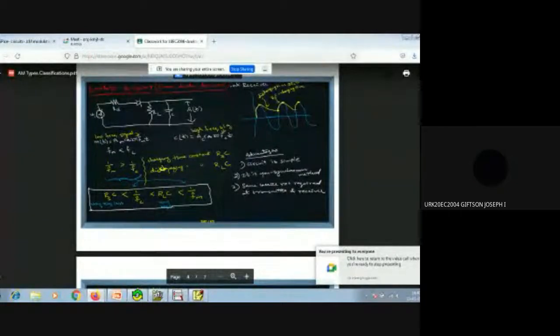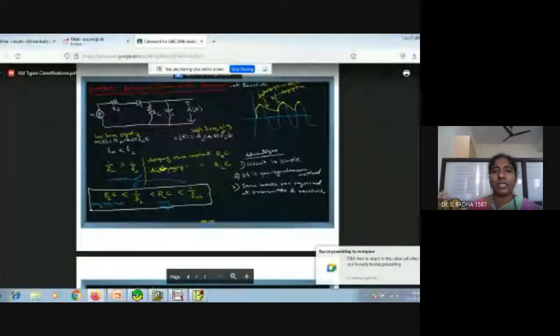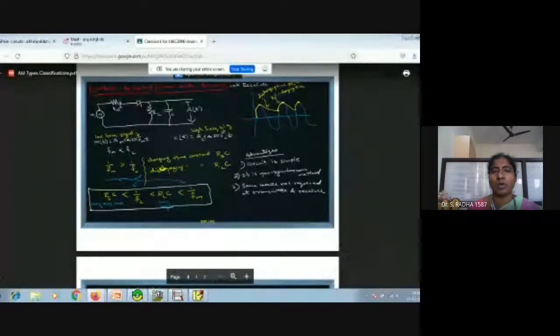So we have to give the modulated waveform. For the envelope detector, we have to give the modulated waveform. Then the envelope detector contains one diode, resistor, and capacitor, and after the capacitor we will get the demodulated waveform, this yellow color. And this RS is a very low value, a very small source resistance, to avoid some noise, etc. It is very less value, so it is optional. RS is optional. So I will connect only the diode, R, and C.